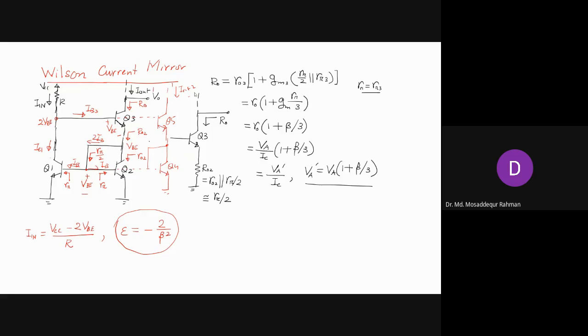So basically, we introduced current sources and current mirror circuits, how to construct the different current sources and current mirror circuits, and how to improve the performance and reduce the error by introducing the emitter resistance and or cascode configuration, and then finally the Wilson current mirror, how to steer the current for multi-stage amplifiers.